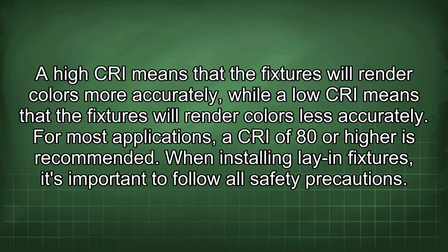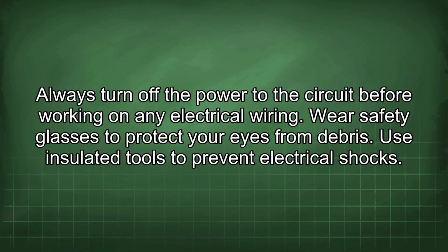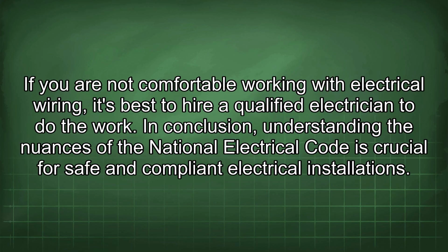When installing lay-in fixtures, it's important to follow all safety precautions. Always turn off the power to the circuit before working on any electrical wiring. Wear safety glasses to protect your eyes from debris. Use insulated tools to prevent electrical shocks. If you are not comfortable working with electrical wiring, it's best to hire a qualified electrician to do the work.